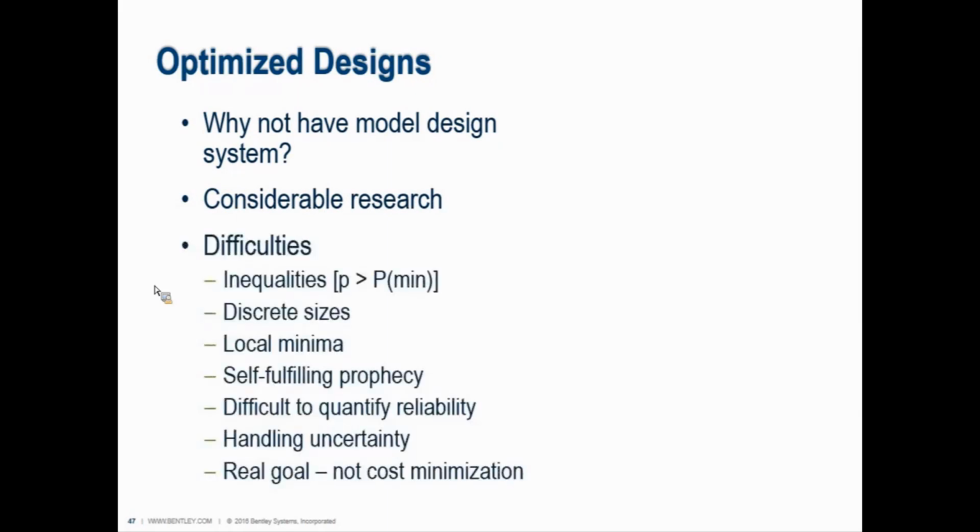Well, there's been a lot of research. Part of it is how to define the pressure benefit across the whole system, and how do you accurately say, well, this hospital needs to get better pressure than this car wash facility? You as a modeler would know one is more important than the other, but the hydraulic model isn't going to know one type of node needs a different type of pressure over another, and make that decision.